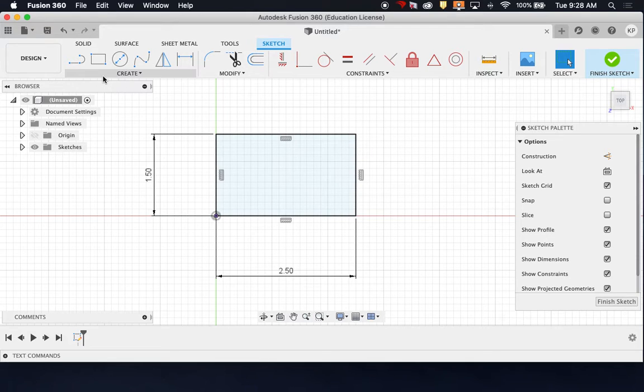We're going to then use the line tool, and what we're going to try and make is a little kind of U-shaped bracket. So we're going to just randomly draw a U-shape in there. So I'm going to click anywhere on this line. Just make sure you get that X, and that way it tells you that you're crossing the line. And I'm going to drag down, making sure, you see how it kind of sticks to 90 degrees? So make sure it snaps to 90 degrees, and any length is fine. Just place it, make sure it snaps to 90 degrees again, and back up until it snaps to that line. So now I've just randomly drawn in that U shape.